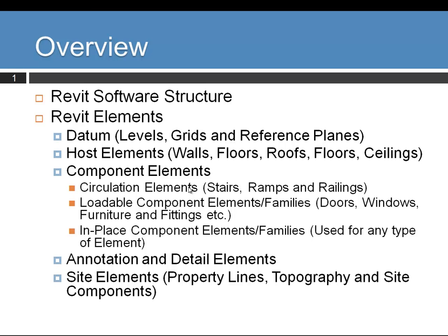We're going to spend most of the time over the next week or so looking at those things, but also starting to look at component elements, which are in general things hosted by those bigger elements, but can also cover things that are hosts themselves, and that's where it can get a little bit confusing, because stairs can host railings, and so can ramps, but they're still thought of as component elements.